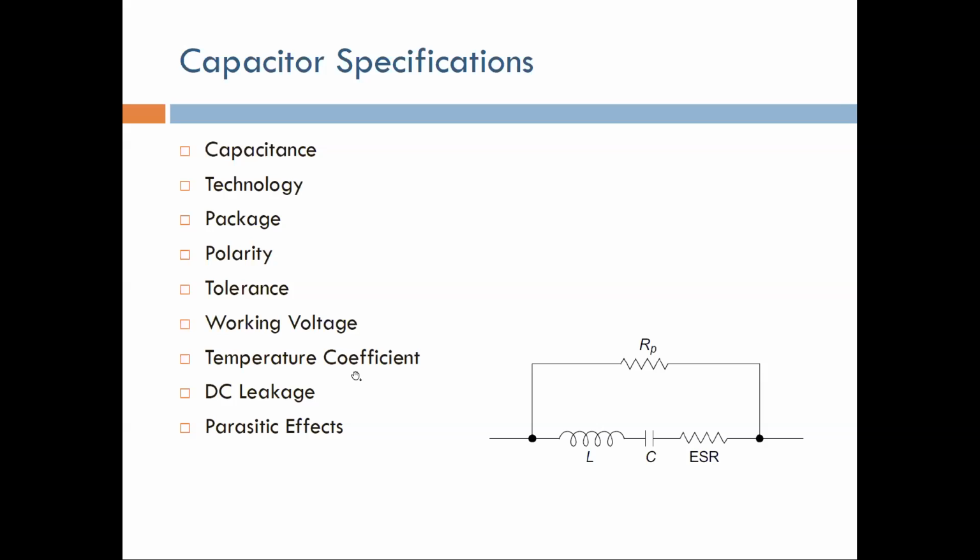It's not as critical as the resistance because usually it's affected only by the room temperature. It's not like the resistance, where the resistance itself creates temperature, or if you use it a lot, it's going to have a higher temperature after a while. No, it's not like that here. It's just a matter of the temperature coefficient relative to the ambient temperature. So if I use it in a room that has air conditioning at 20 degrees centigrade, it's going to be a little bit different from using it outside, like in the summer here in Jeddah with temperatures like 40. It's a slight difference, but it's not that big of a difference.